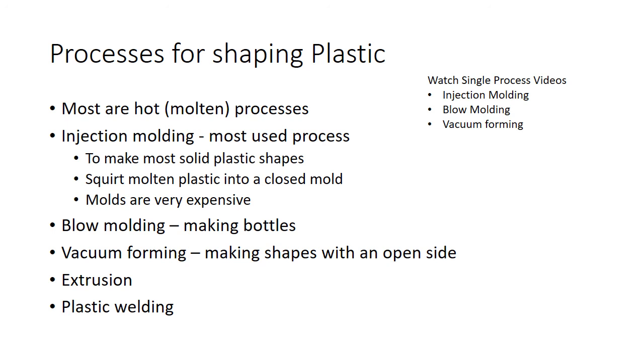They would break, and he had an 8-hour-a-day job welding plastic. And then basically you heat it up with what's kind of like a hair dryer, and then dab in extra plastic like a welding rod, and you build up plastic on it.